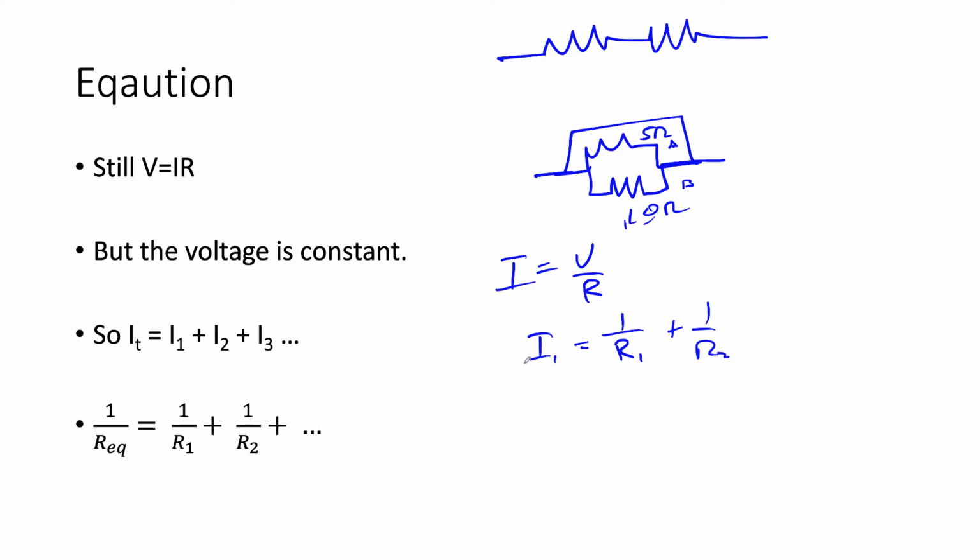And that means the total resistance is going to be Req. So with these problem sets, do not go R1 plus R2 equals Req, because that's wrong. And when you add them, don't do this either, because that will be wrong. So the best thing to do is convert everything to a decimal and do the inverse of the decimal.